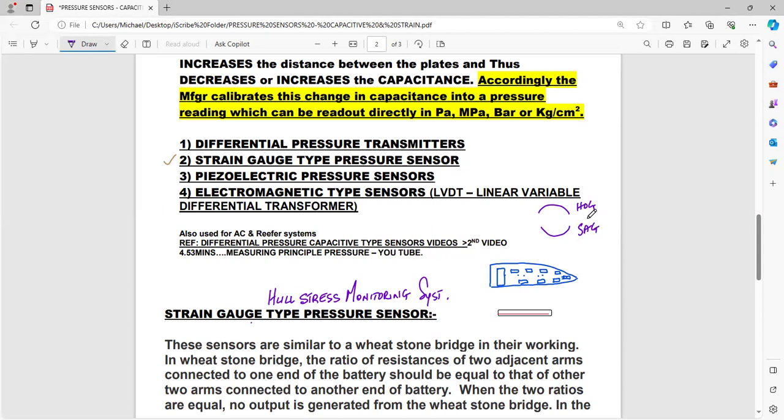So your ship hogs and sags in very rough weather, which means a lot of stress and strain is coming on your ship's hull. It can break in two at any given moment, especially if you are carrying iron ore. Your ship's hull becomes like a dry twig. Bend it too much, whether hogging or sagging, and it's going to snap in two and sink.